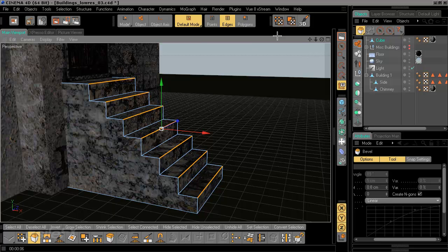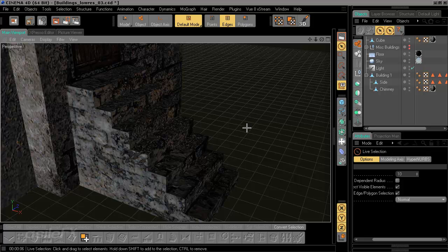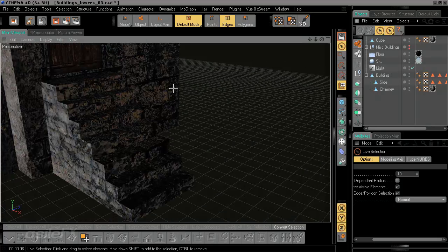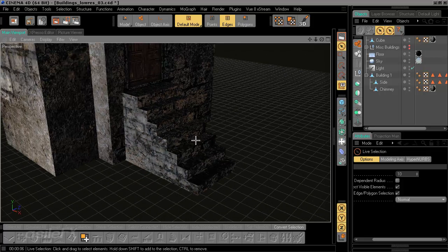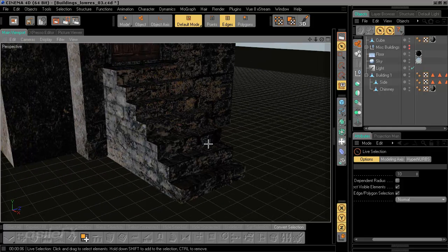I want to note, just because we're using the same material doesn't mean that we can't generate some more specific maps, specifically the normal map, and then copy and paste the material to have a specific normal for that object, but still everything else will run through the texture. And essentially just creating a mix. And there is a technique you can use for the normal map to avoid having to create additional polygons, and it has to do with using that UV edge that's generated from the texture.